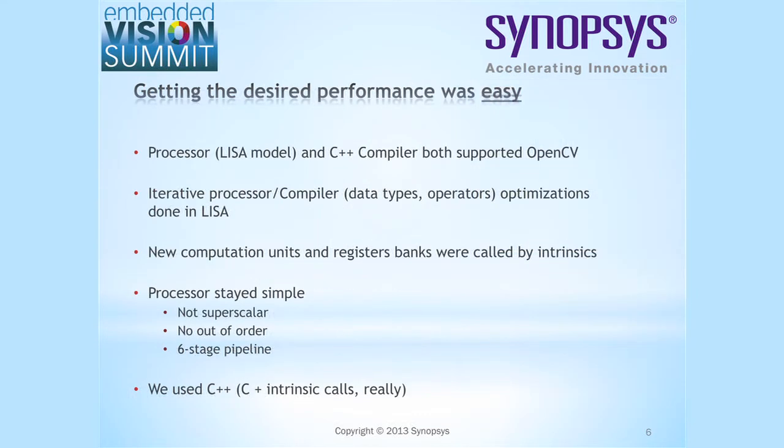And so just to reiterate the performance, this is easy because we could measure on the simulator. We did some iterative operations. I'm just going through this really quick. We put in bigger registers, some custom ops. And we're also not overdoing the processor design. We're not touching the superscalar architectures. We certainly don't want to do out-of-order processing, and it's a 6-stage pipeline out of the book, really. And we also are not looking for a revolution in software development. We're using C++, really C with intrinsics, because we removed all the C++ code with the dynamic memory management.